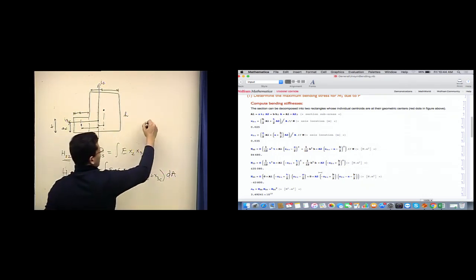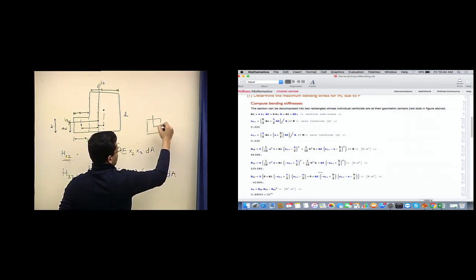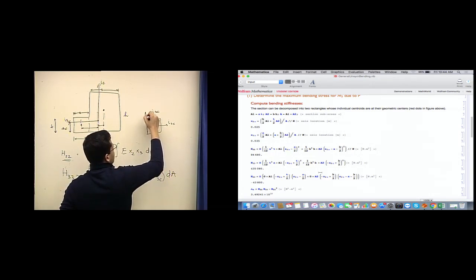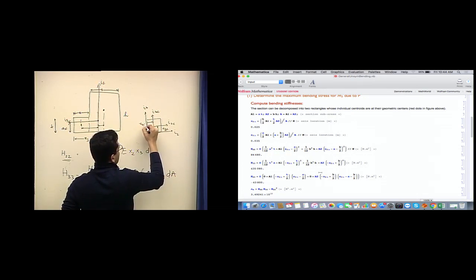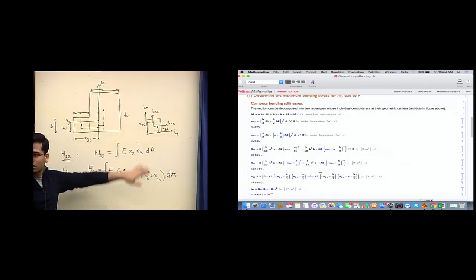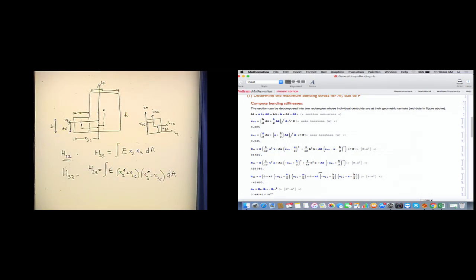So what I'm doing here is, if I have a cross section, the cross sectional centroid is here, I2c, I3c, and then I have this reference frame, I2, I3, and this distance is x2c, x3c, and then this distance is x2c. So this is my configuration. Yeah, go ahead. Does it matter when you're doing x2 star plus x2c, does it matter if it's plus or minus in there? It matters where you are going, like you are coming from the centroidal reference frame, or you are going to the centroidal reference frame.